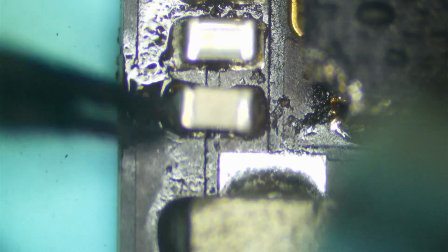So you do notice with the bent tip nozzles, it does cut down on that energy pretty significantly, and it does take a little bit longer to heat soak it, to remove it from the donor board. And I'm blowing my air away from my NAND, just like that. And this is now in place.